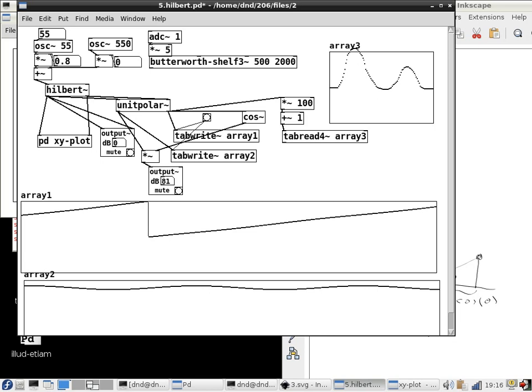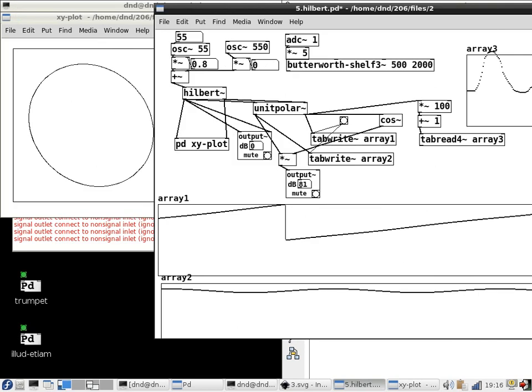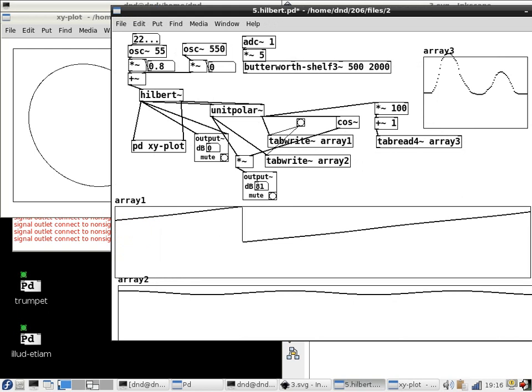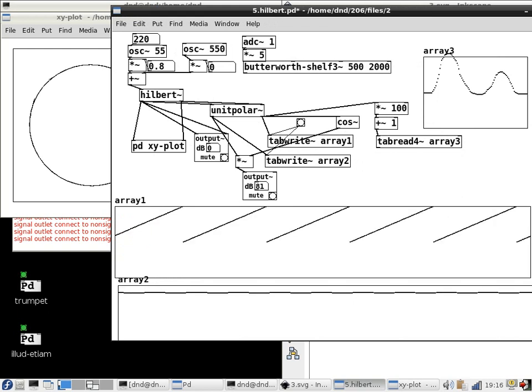I think I got this frequency so low that the filters aren't quite 90 degrees out of phase, so this isn't quite a circle, and this is gently drifting. So let's give myself a nice reasonable frequency. A decent frequency means I have decently constant amplitude. Now I'm listening to r cosine theta, but I can always listen to something else.